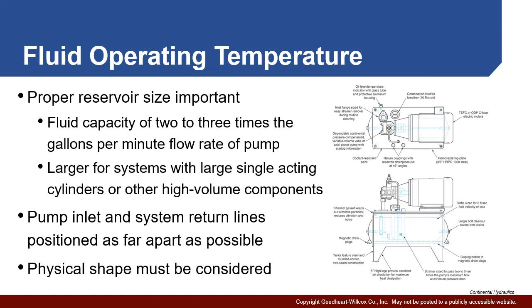This gives us a chance for things like contaminants to settle out, but also a chance for the temperature to be regulated. Keep in mind this recommendation of the 2-3 times does depend on the system, however, and if you have systems that are very high volume, something like a large single acting cylinder, a large hydraulic ram, where a lot of fluid might be drawn into that component, you're going to need a larger reservoir.